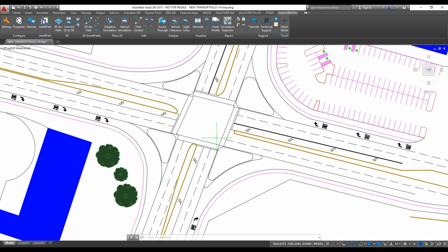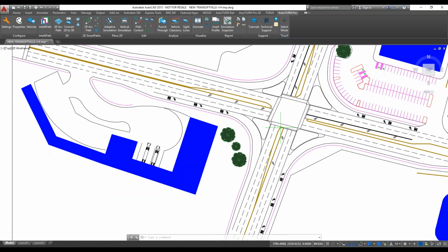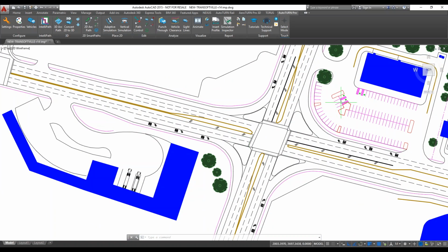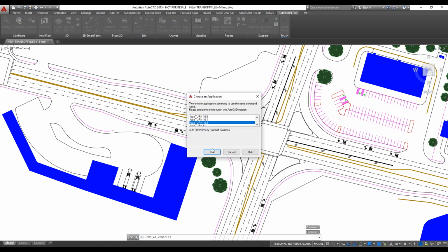We know a template will work or will help us simulate vehicles here. However, if we're doing something that involves reverse or more complex turns, we might run into trouble, or it might be too complex for us to simulate or model. AutoTURN is also capable of generating turning templates for design vehicles, if that's what you would like to use.